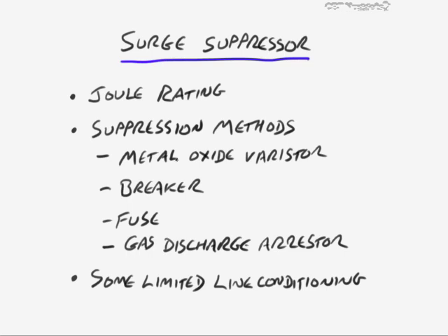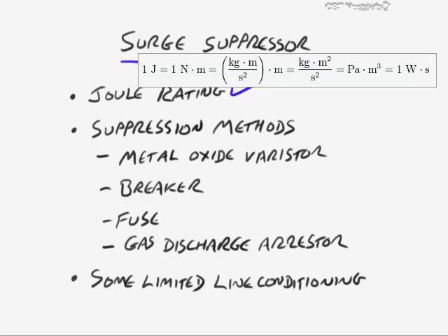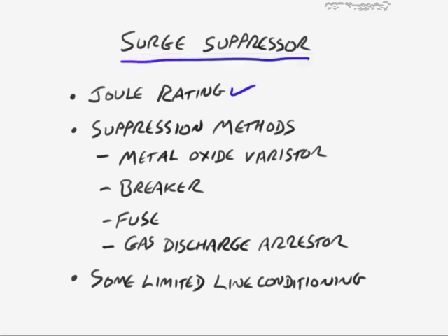So it's very important to have a surge suppressor, and these are going to normally be rated on joule ratings. And if you go look at the good ones, then they'll say it's rated to 500 joules or 1,000 joules or something like this. And you might wonder what's a joule? And by the way, didn't I misspell it? Actually, it's named after somebody that's named Joule, James Prescott Joule, and he came up with this formula right here to calculate what a joule is. Okay, I have no idea what that actually means, but if you can get back with me and let me know, then I'd appreciate it. No, actually what that is is just a measure of the work that's required to continuously produce a watt of power for 1 second. That's all that really is. And so they're calculated on that basis.